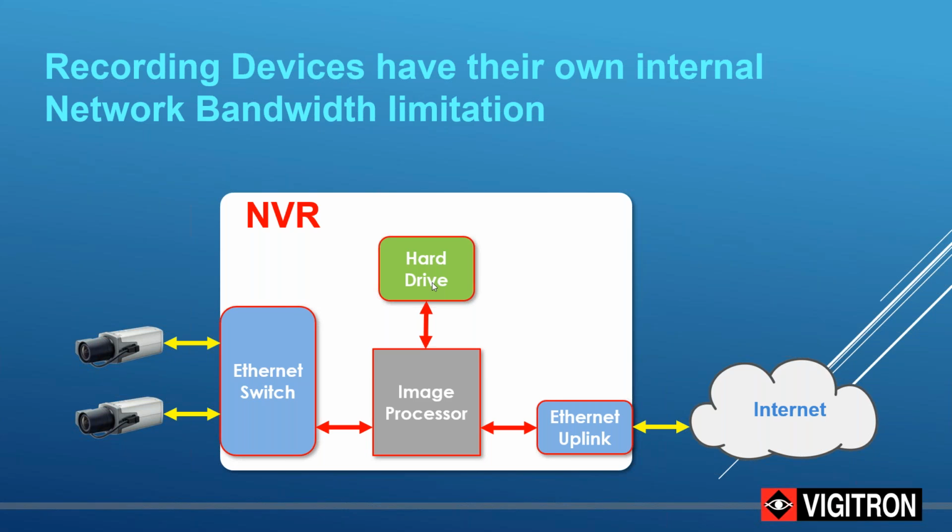So when we talk about 100 Mbps, we actually only have 50 Mbps available for the transmission of a camera. When we talk about 1G, we're basically down to 500 Mbps. Now, for a single camera link to a switch port, 50 Mbps is a lot.